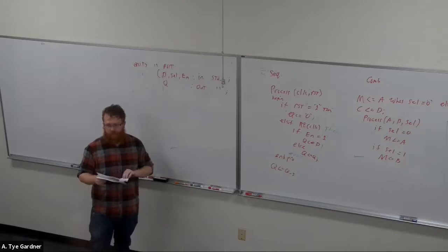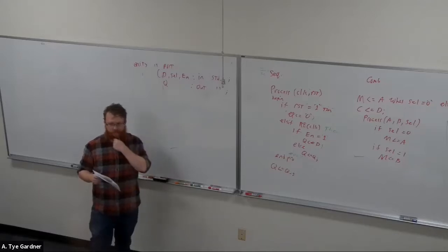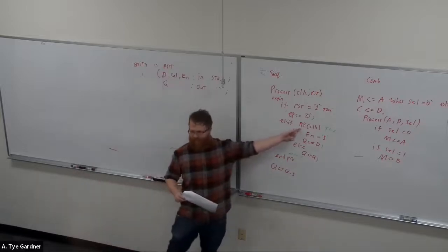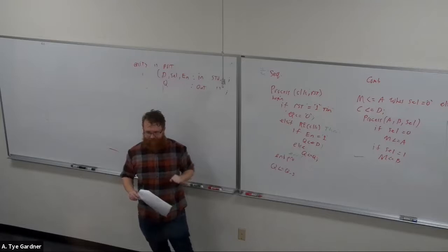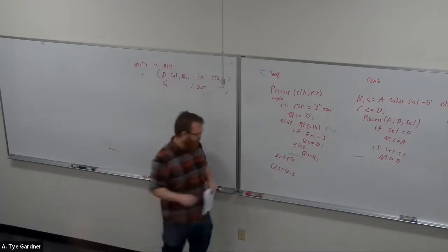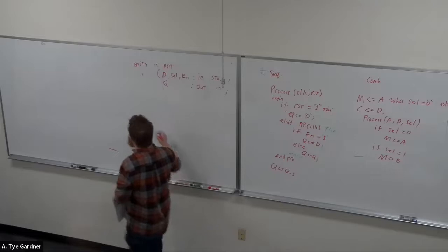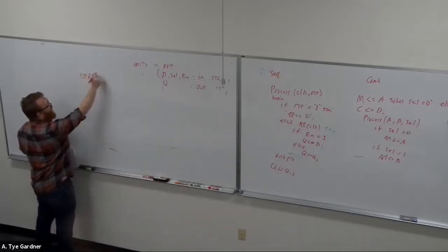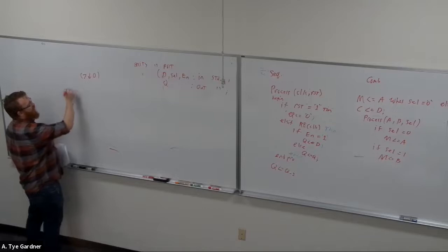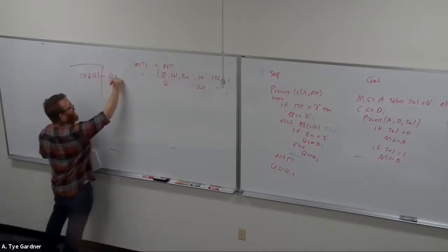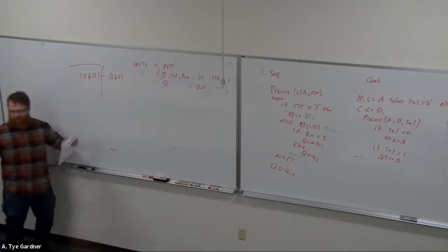Question? Oh, I was just gonna say, when we write VHDL code, do you care if we use shorthand, like 7 arrow down? Not at all. Any shorthand that I use, like RE, is perfectly allowed. A down arrow for down to is perfectly allowed. Make sure that you understand that if I give you 2 entities and one of them has 7 down to 0, and this is a port, and then I have a signal that is 6 down to 0, that doesn't work, right? It's unhappy.